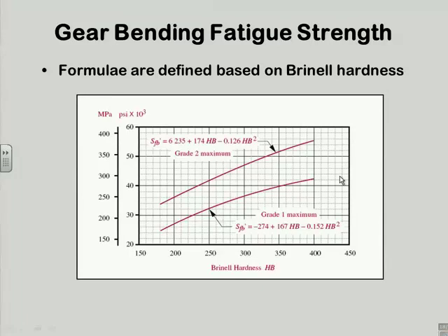So it's really simple. If I have a piece of steel that's in two pieces, it broke out of a machine, and I've been asked to do an analysis of this and redesign it so it doesn't break. The first thing I say to the guy is, do you know what kind of steel it is? I don't know. Just came out of the machine. No idea. I bought the machine used. Not a clue. So I could take that to a Brinell testing machine. I can do a hardness test in literally 5 minutes, take that number, multiply by 500, and I've got an approximate tensile strength for my material. So it's a very, very handy way to get a rough number. There's a good bit of noise in it, but it's better than nothing.